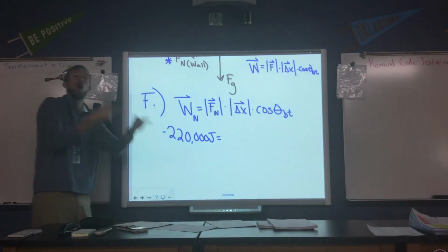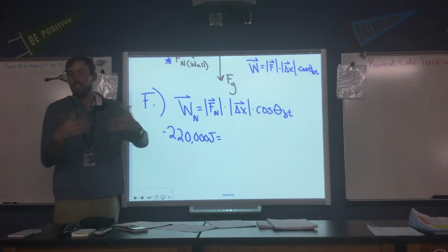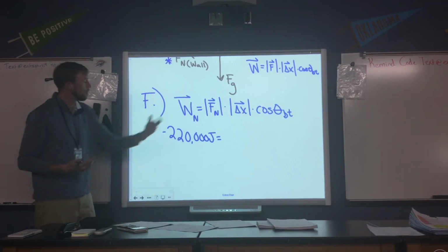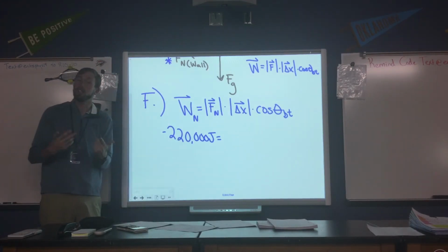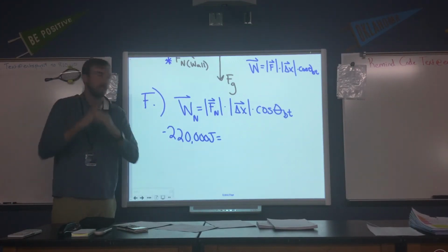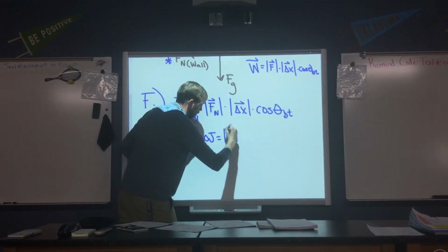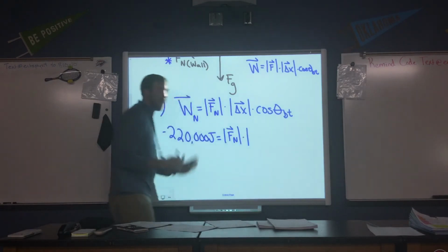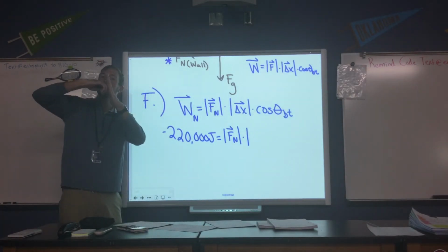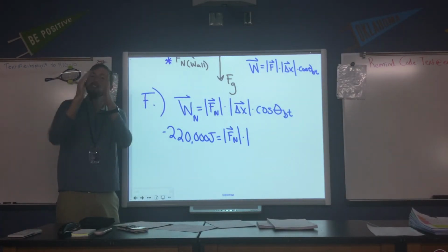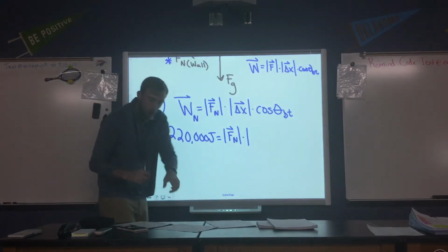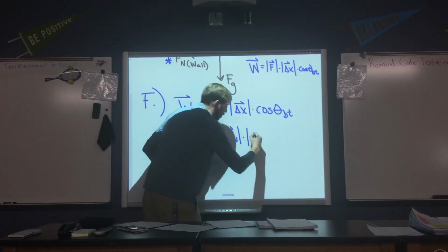The wall takes away all the energy of the car. Specifically here we're talking about kinetic energy. The wall takes away all of the car's kinetic energy because the car comes to a momentary stop. Now the force we're not sure about, so I'll leave this just as Fn. Delta x, that's going to be how far our car moves while it's hitting the wall. That would be the length of our crumple zone, which for car 1 was 0.8 meters.